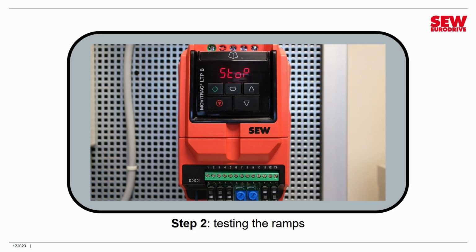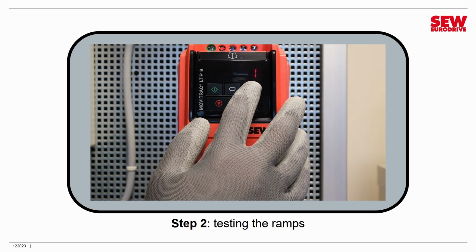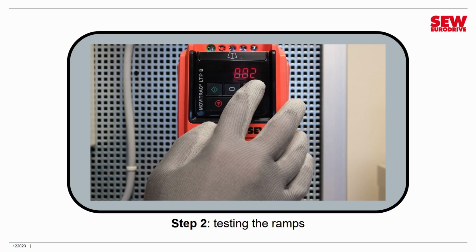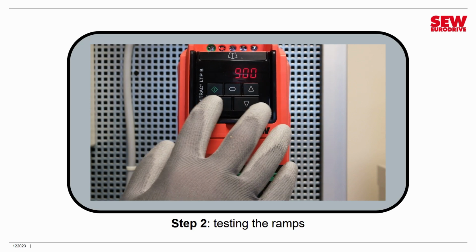All right, the first thing I'm going to do now is turn digital input 1 on to enable my motor, and I'm going to press the start button. And now I'm going to use my up and down buttons to adjust my speed, so I'm going to get my speed tweaked to exactly 900 RPM. All right, now we're exactly at 900 RPM.